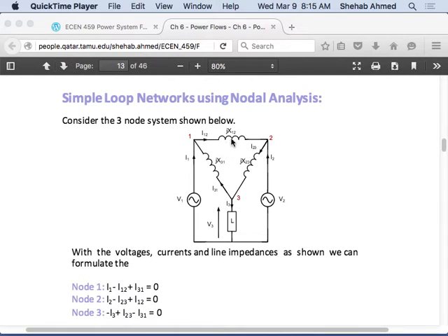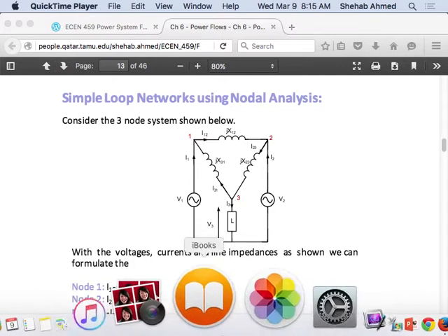It's the same. We forgot about the resistor here, but that doesn't mean that's always the case. Sometimes we will consider resistance here, right? This is only the imaginary component, which is only the reactance, but in certain cases we will consider both. There's an example later on. When we derive the equation to solve the full system, we will consider both resistances and inductances present.